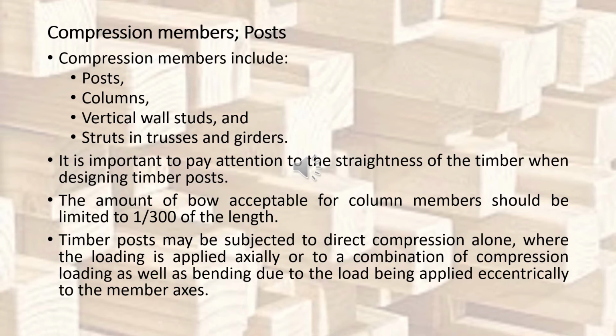Timber posts may be subjected to direct compression. It can be only direct compression where the loading is applied axially, or it may be subjected to a combination of compression as well as bending, depending on whether the load is being applied axially or eccentrically on the members. If you've got some degree of eccentricity, definitely you're going to have a bending moment induced in addition to the compression forces.